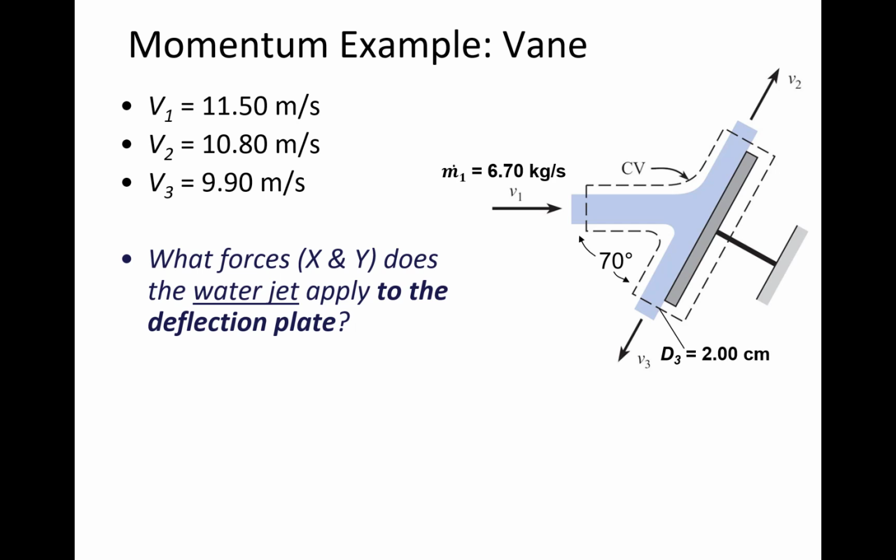Jeremy's got it. He says A1V1 equals A2V2. And that's true if there's only 2 fluid streams, as we've seen before. But now here, there are 3 fluid streams. So, Jeremy, how would you, in this case, adapt what you just wrote in the chat box to this particular scenario? Because in this case, A1V1 would not equal A2V2. But I get what you mean. You were saying flow in equals flow out. And that's the overall principle that, yes, still applies here.